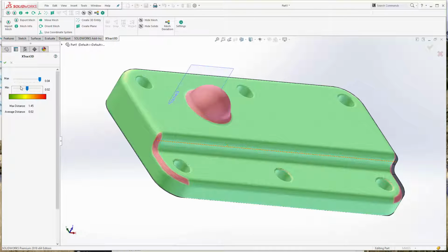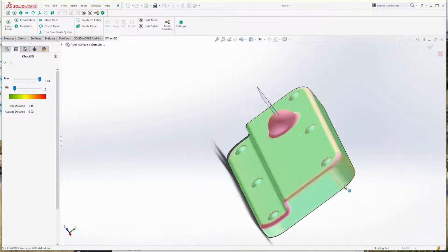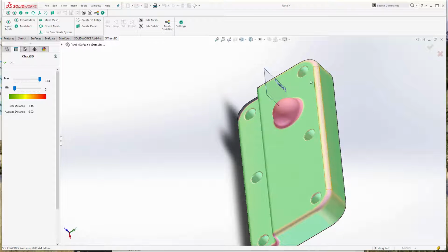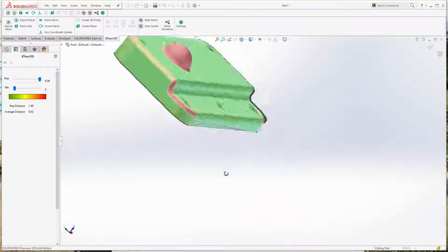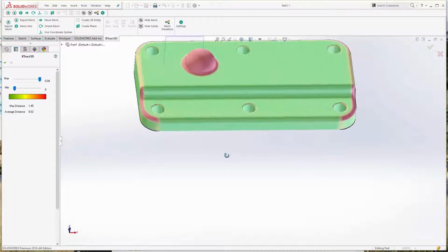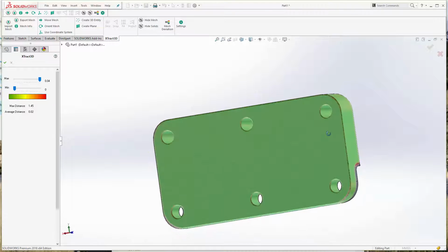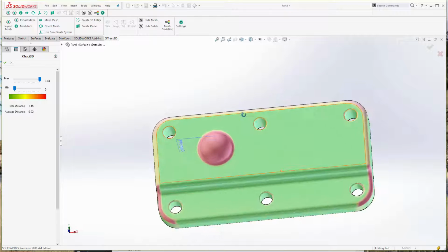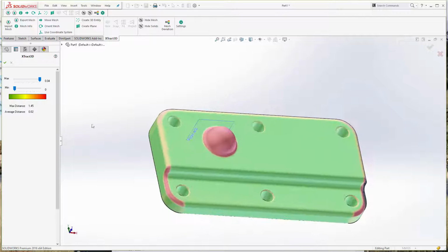Here we go, the comparison chart for the scan. You can see the part that's probably the furthest off is the circle, so we must have missed there. And this area here wasn't too bad because I guess we eyeballed it pretty well, but this area is pretty bad because we did absolutely no filleting of it in the CAD file, whereas in the scan data, obviously there's a lot more in there. The rest of it looks pretty good. I think this is a really simple part that was geometrically almost perfect. So when we did the CAD of it, pretty much everything was good.